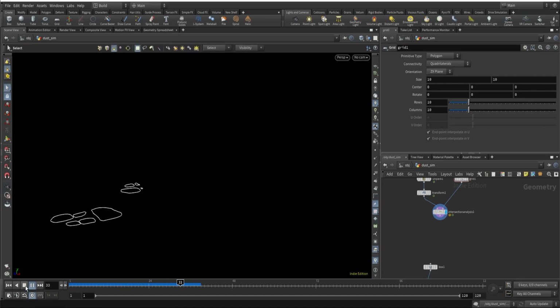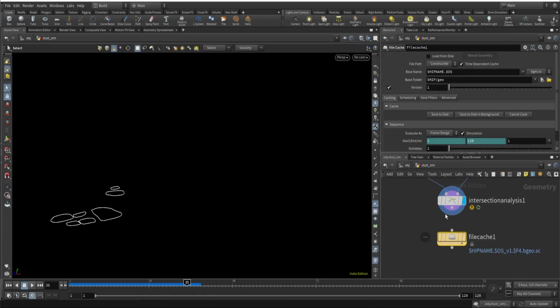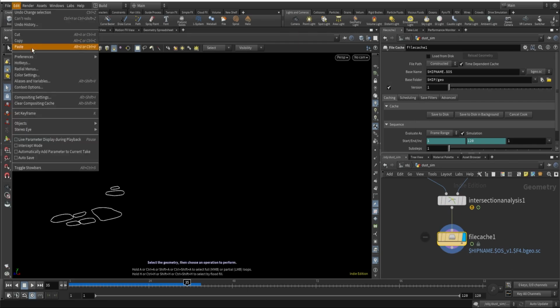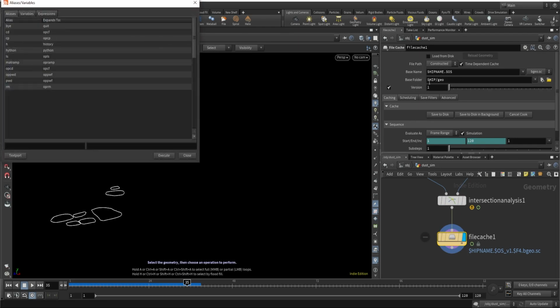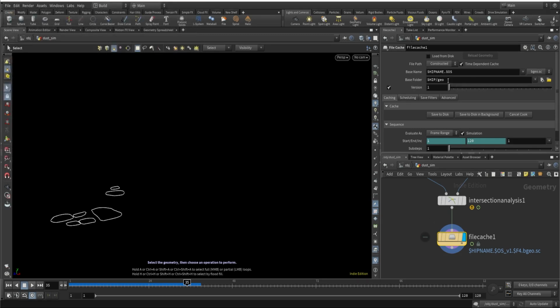So it's taking time to load, right? So here I can use a file cache, and I can save this. Remember I was talking about this $HEAP? It's a variable. If I go to edit, aliases and variables, and type this $HEAP, it will read some path. But which path? To visualize that, I can just go over here, and HEAP will read this master folder I have created. So if I cache everything over here and copy paste this folder anywhere in the drive, it will auto sync this path and auto construct this folder and everything. But I don't really want this.